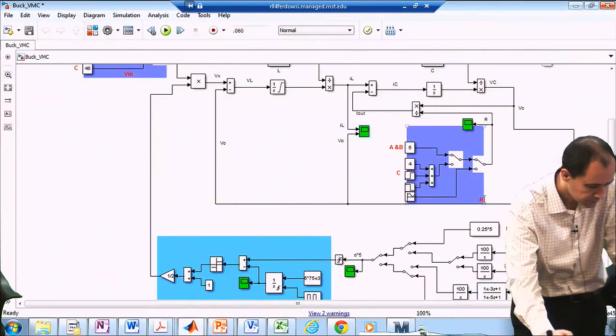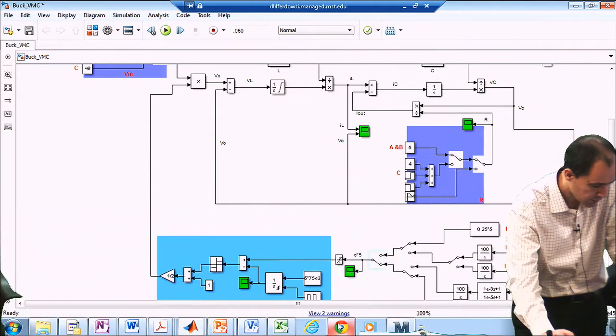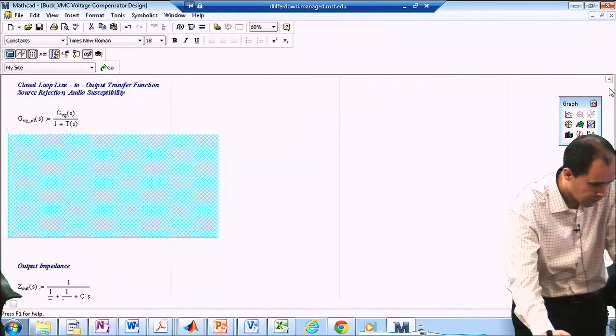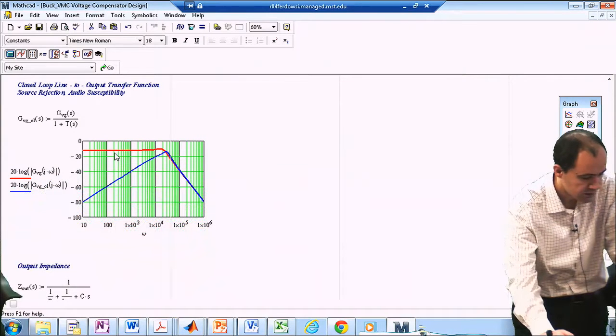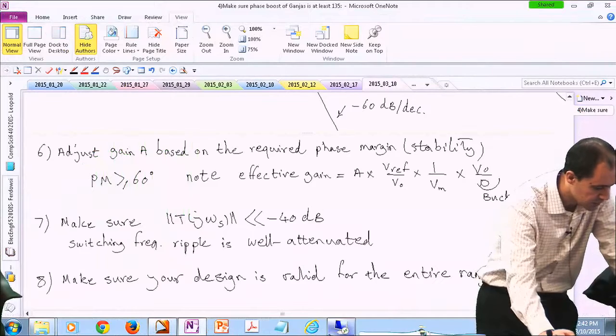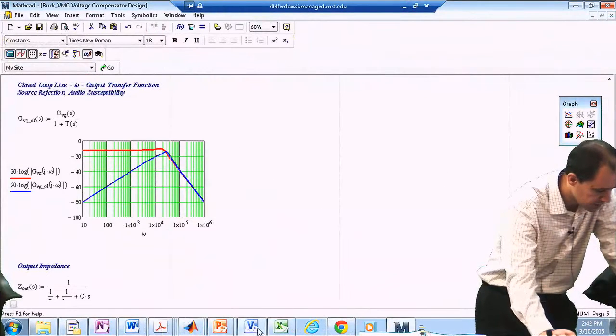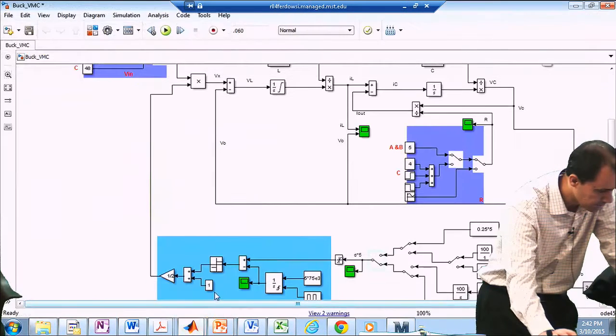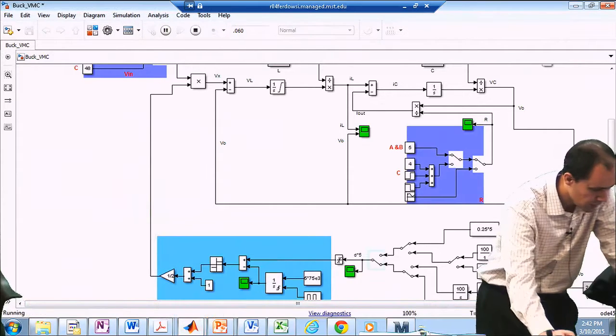Now, if you switch it to the good compensation, because I'm doing an extra amount of attenuation at 120 hertz or 100 hertz, whatever it is, I would expect things to get much better. And let's see. So now my loop is closed.